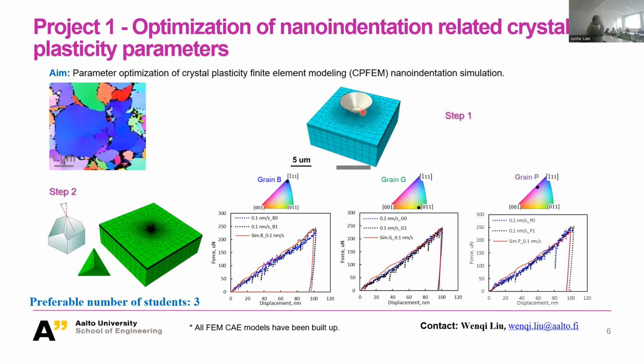So this is a complex model. You have no idea at the moment, but it's just a bunch of equations. It's a simple equation, F is equal to m times a, and then you can easily correlate F with velocity, acceleration and mass. But here the connection is not that straightforward. You need to solve a lot of differential equations. But in the end, you try to correlate the force from that test with certain material parameters, with certain material microstructure. Those correlations were described by this so-called crystal plasticity model.